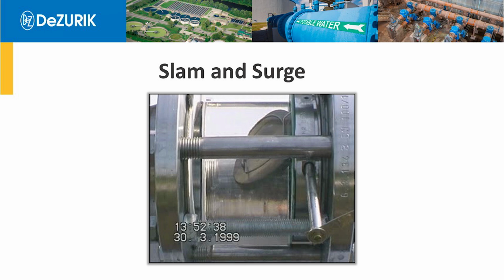The check valve is in the open position, and you'll hear the check valve slam. And then what you'll see is after the check valve closes, you'll see the surge wave that we discussed, which is the upsurge and the downsurge. And each of those pressure waves will become less in intensity due to the friction in the pipeline, eventually bringing that fluid column to rest.